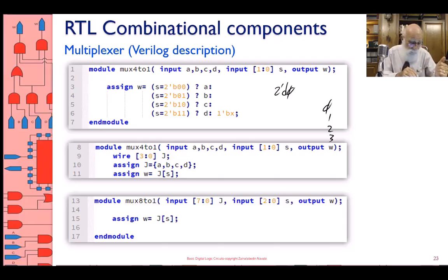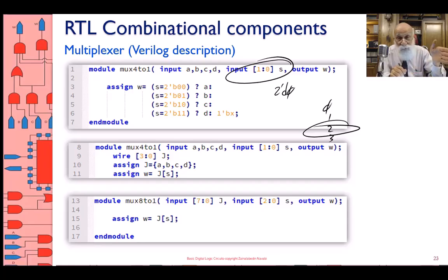When you say 2'b00, you are saying 2 bits, binary 00. S is a 2-bit vector, and therefore 00 goes to these 2 bits. When you say 0 or 1 or 2 or 3 without any size and the base of the number, it gives you a 32-bit binary number, and then it truncates 30 of them and gives you only 2 bits. So why bother? Why not specifically say I need 2 bits and these are the 2 bits I want?